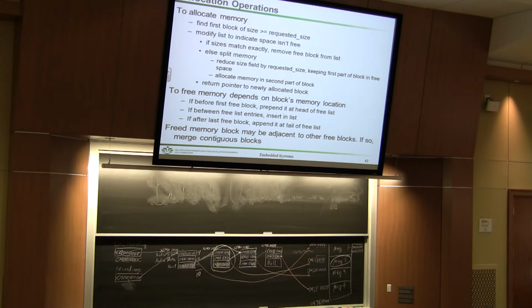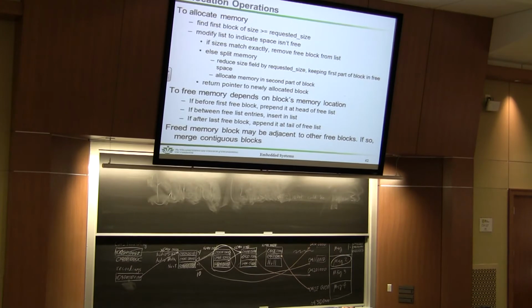But in an embedded system, that's going to be really bad, right? Because eventually you have to give up. And usually that means that you reset or the system has to reset itself. We'll talk about that later when we get into watchdog timers, which is almost at the end of the semester. So when you're allocating, you continually allocate until you have no more free memory. There are also other types of facilities that you could use to squish up the memory. In other words, go back and figure out who's using what and try to put as much free space together.